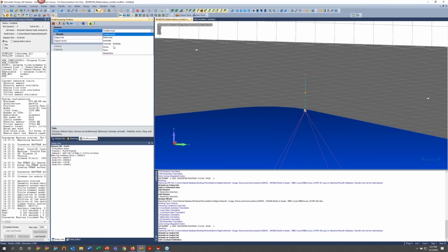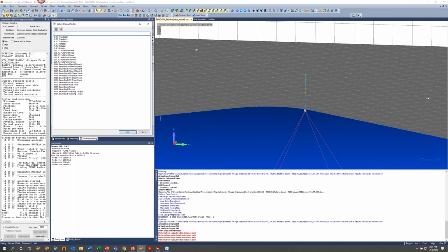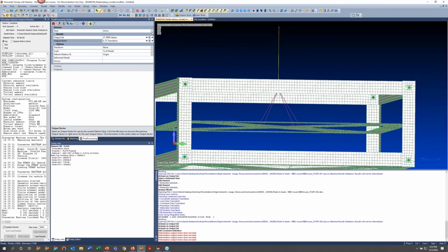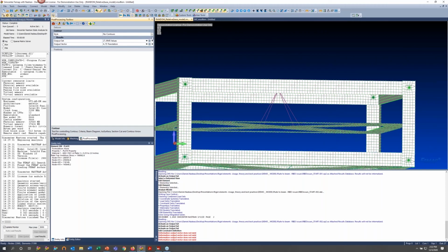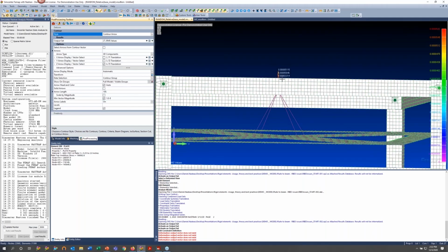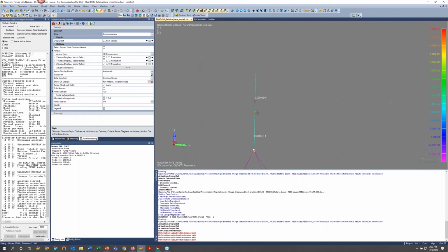And for post-processing, you do have the ability to plot. Maybe I'm interested in T3 translation. I'll be able to plot this as a contour arrow plot. I don't want it deformed, undeformed. Contour arrow plot to see what's going on. Not section cut, contour arrow. There we go. So now I have an arrow that's showing me the displacement of that entity. So now I have it available to post-process, and I have the relative displacement of that node.